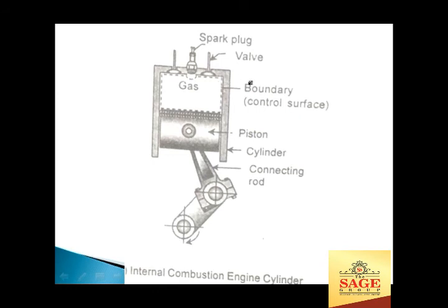You can also take another example of an open system. Here there is some system, we can see this is the gas, and this gas is the hot gas. Take the example of the IC engine. This is actually the case of the auto engine or petrol engine. These two valves are there, and there is one spark plug. In the suction stroke, the inlet valve will open and the air fuel mixture will enter here. When this valve is closed, you give some spark, and the combustion of the air and fuel, that is the petrol, will take place.